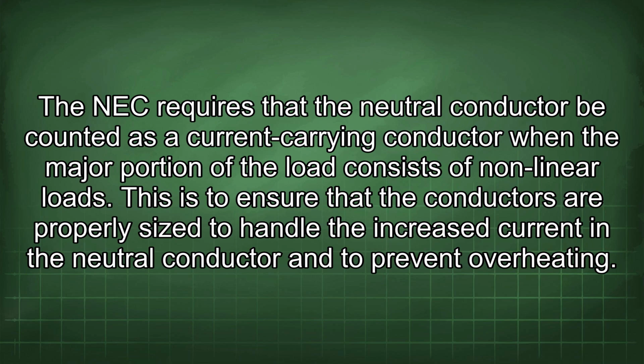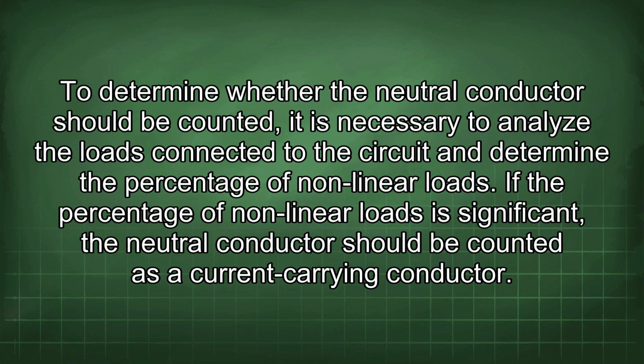This is to ensure that the conductors are properly sized to handle the increased current in the neutral conductor and to prevent overheating. To determine whether the neutral conductor should be counted, it is necessary to analyze the loads connected to the circuit and determine the percentage of nonlinear loads. If the percentage of nonlinear loads is significant, the neutral conductor should be counted as a current carrying conductor.